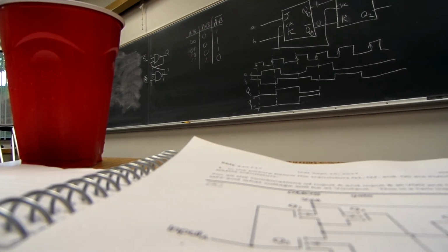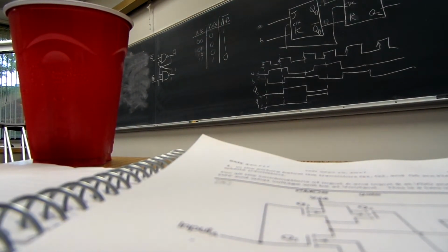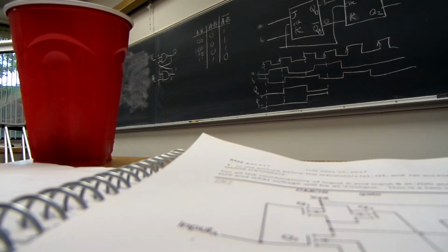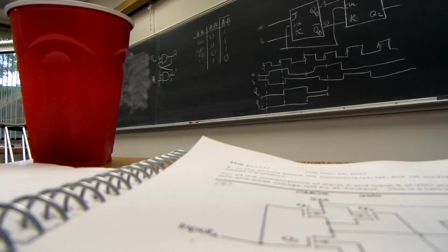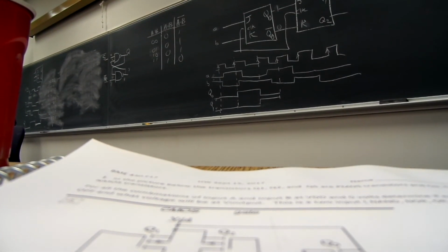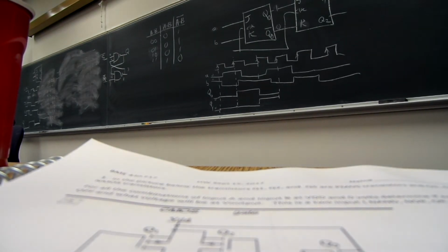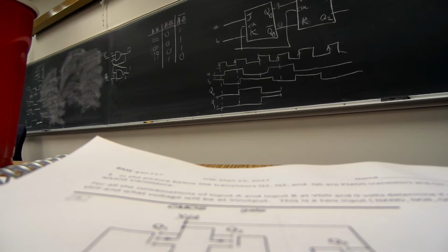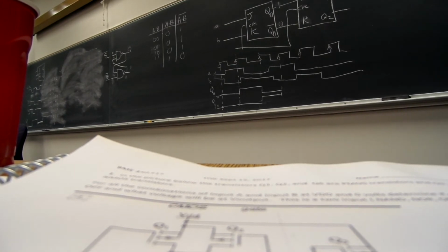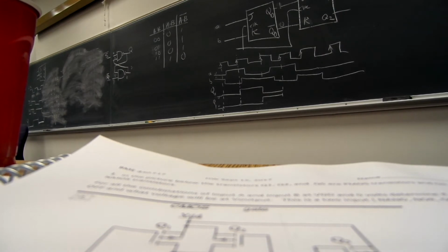And therefore, what resistance? 400 ohms for our logic level devices, right? We can get FETs that will have on resistances down in the milliohm range, but they're much, much bigger devices. Gate to source voltage 0, what's the device? On or off? Off, and therefore we model it as an open circuit.